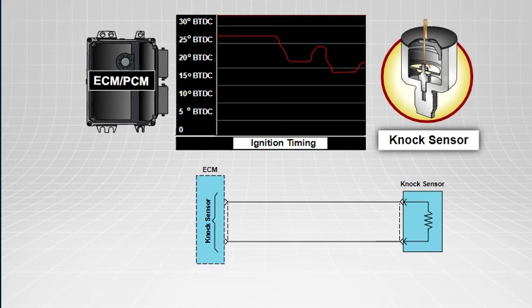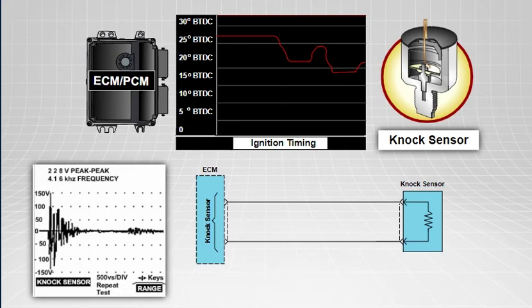At idle, the signal circuit should read less than 1 volt. If knock occurs, voltage approaches a maximum of about 4.5 volts. On an oscilloscope, you can see that the initial shock deforms the sensor and the piezo-resistive elements generate high voltage. As vibrations subside, voltage approaches 0.